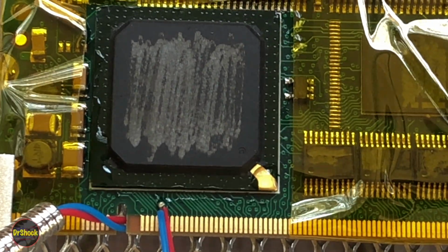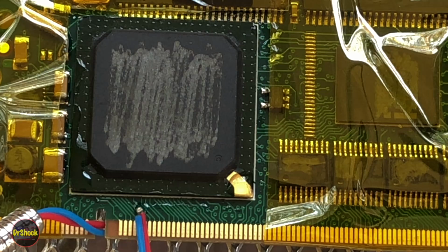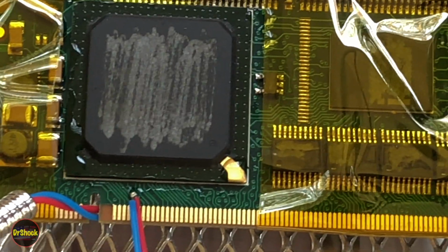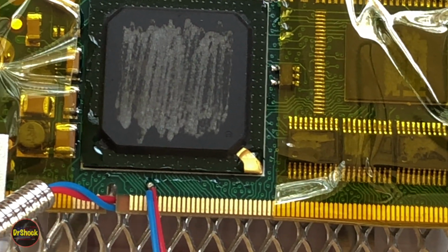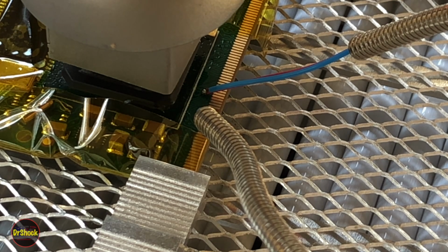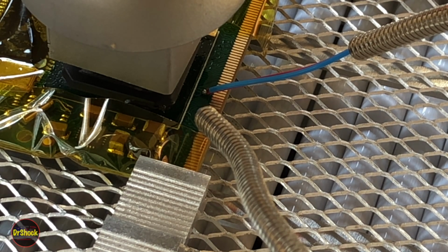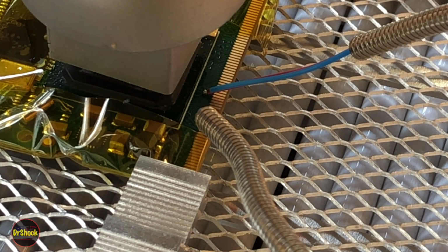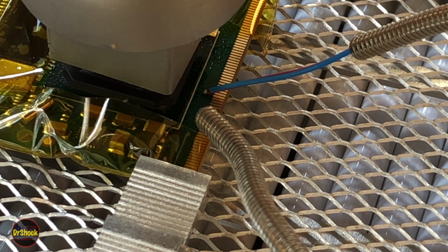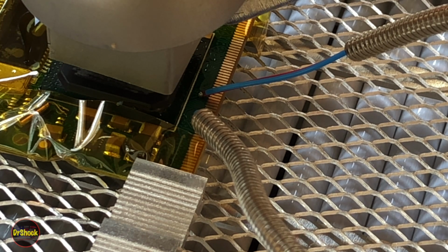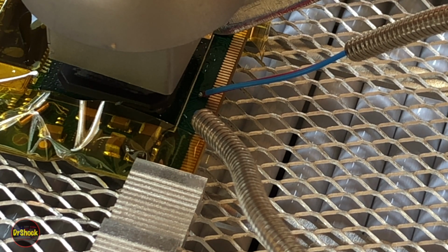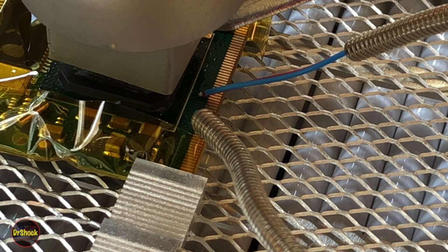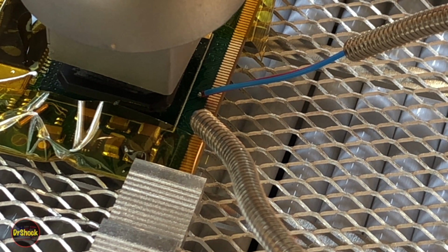All right, guys, at this stage we've added some flux all along the edges of the device so that can wick in underneath the balls as we get almost to the point of moving the hot air gun into position. All right, guys, we've got the hot air gun into position. She should liquefy pretty quickly at this point. We're just going to come over and see if we can see movement now that we're at the right liquefaction temperature of the solder. Right there. So you see how the surface tension on the chip is? At that point, we know we've done a secondary reflow.